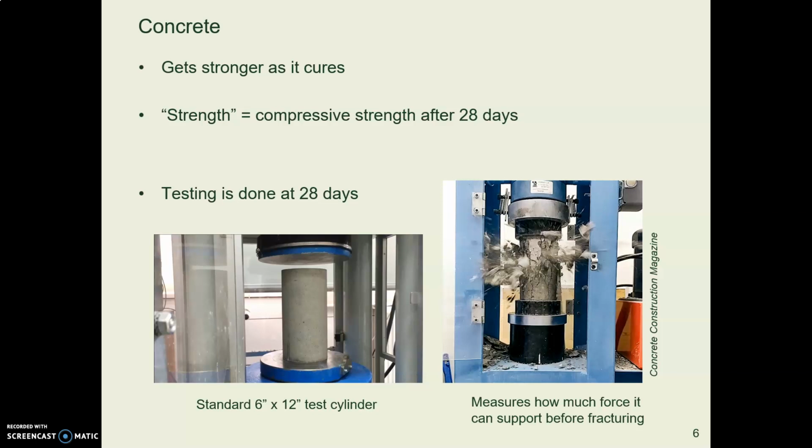And here's the deal. Concrete, after you pour it, begins to cure. And it cures for many days. And the longer it sits and cures, the stronger it gets. After 7 days, it's got some strength. After 28 days, that's where we consider that is its full strength that we've written into our specs. Now, I will just add, it's going to keep getting stronger as years go by, but 28 days is the mark at which we do our testing.